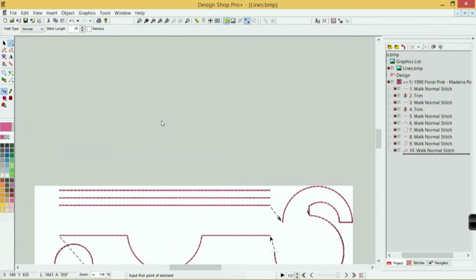So that is how you would use the walk input method. As I'm digitizing, if I make a mistake, I can hit backspace, and it will remove the last input point, and I can continue doing that. If I want to get out of the element that I've created, I could also hit escape, and that would remove the element that I've been creating, but it would keep the tool selected. If I want out of that as well, I would hit escape again. So escape twice gets me out of everything. I don't want to touch any of the input tools. I just want to look at my design again. Let me select that tool again. So again, digitizing along, made a wrong click, I can hit backspace and fix it, continue on, hit enter to complete my shape.